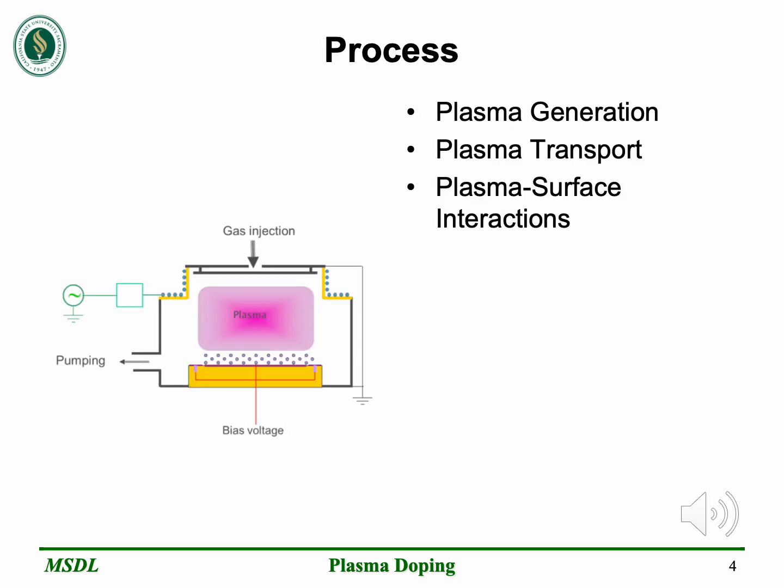The plasma doping process involves three key steps: plasma generation, plasma transport, and plasma surface interactions. The figure shows the chamber consists of a radiofrequency ion source generating plasma which impinges on a wafer that is electrostatically clamped to a plate. The plate and wafer system are then biased at negative potential from 100 volts to 12 kilovolts to extract ions. These implants are typically done with the platen at room temperature or slightly elevated temperatures up to 70 degrees Celsius. So, the first step is the plasma generation.